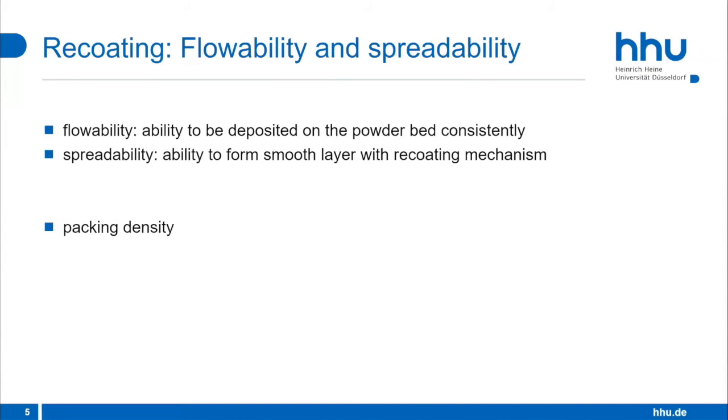And a higher packing density is actually quite important because in this case, we have a higher apparent density of the powder bed. We can get higher drug loadings, and we have also more contact points between the particles that can sinter together. So we get stronger materials.